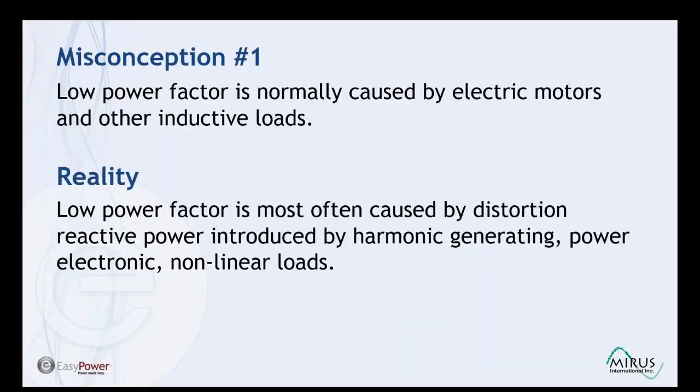So the first misconception is that low power factor is normally caused by electric motors and other inductive loads. The reality is low power factor is most often caused by distortion reactive power, introduced by harmonic generating power electronic nonlinear loads.